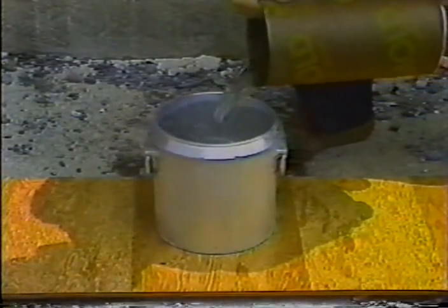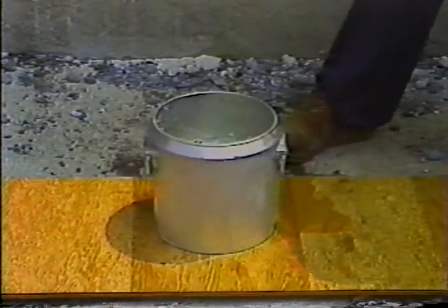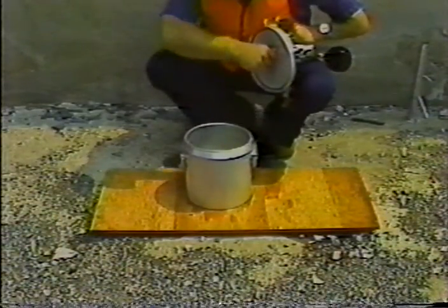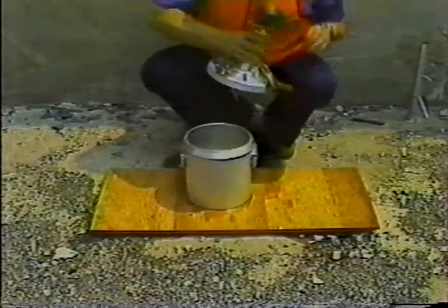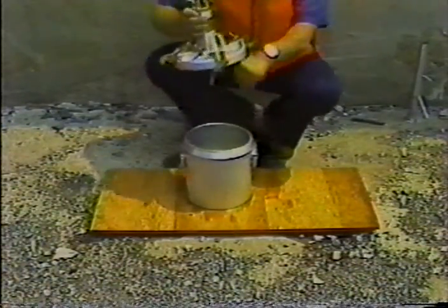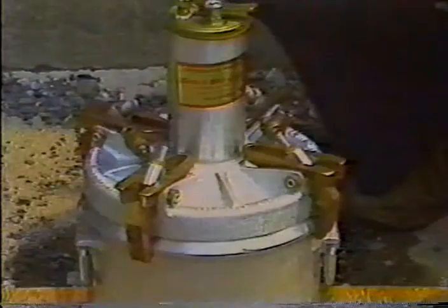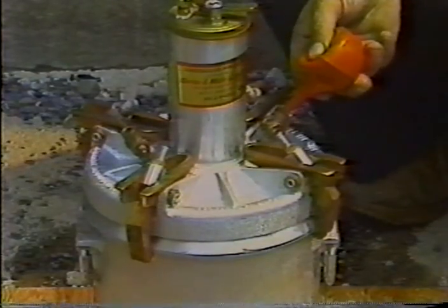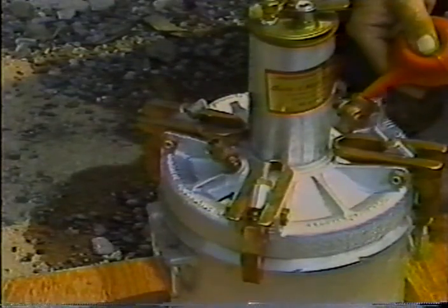But now let's look at the calibration. Calibration is necessary to verify the operating pressure and to check the pressure gauge accuracy. Here's what to do. First, fill the base completely full of water. Screw the short piece of straight tubing into the threaded petcock on the underside of the cover. Clamp on the cover. With both petcocks open, inject water into the petcock with the tube attached below it until water comes out the other petcock.